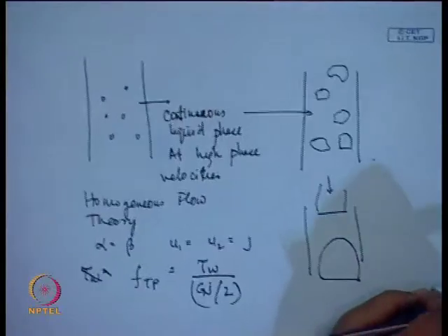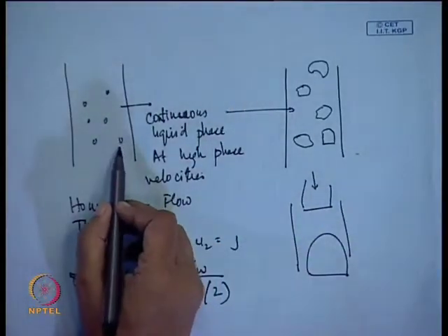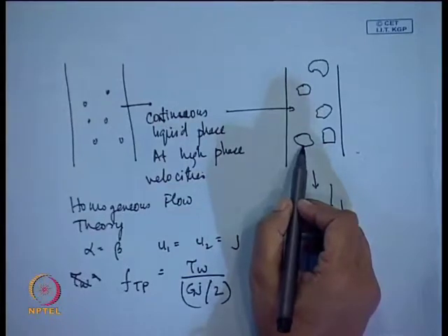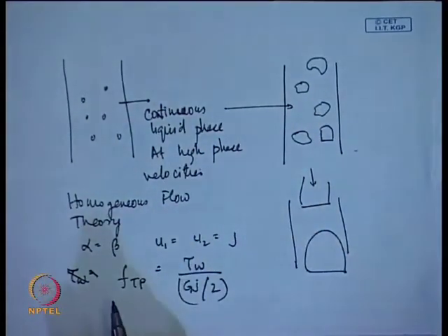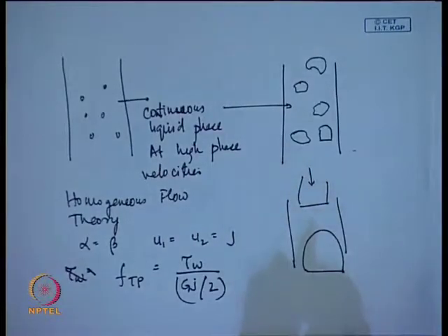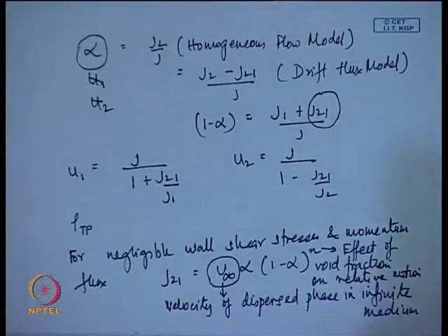It is because, if you see this picture again, it is quite evident that the rise velocity of this particular single bubble in an infinite medium cannot be equal to that of this particular single bubble in an infinite medium, is it not? So, therefore, u infinity and n have to have different values in order to incorporate different ranges of the bubbly flow pattern.